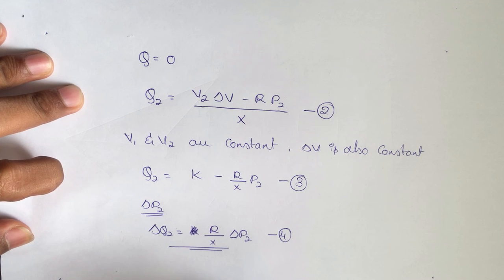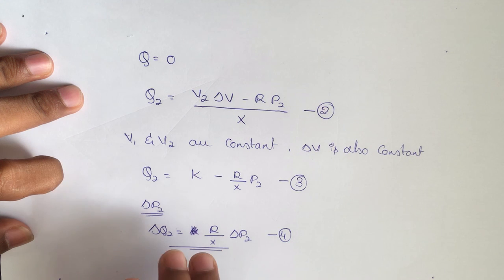And here we can state by this equation that we can control the voltage by injection of reactive power of correct sign. By injecting a reactive power of correct sign, we can control the voltage. This is about the dependence of voltage on reactive power for an interconnected system.